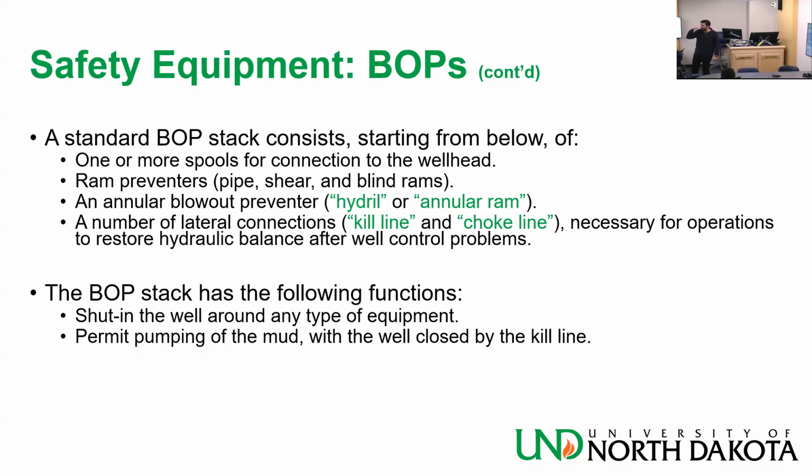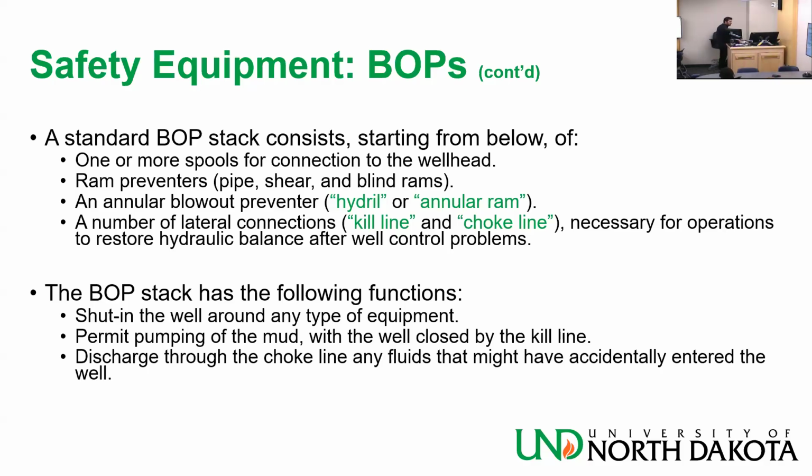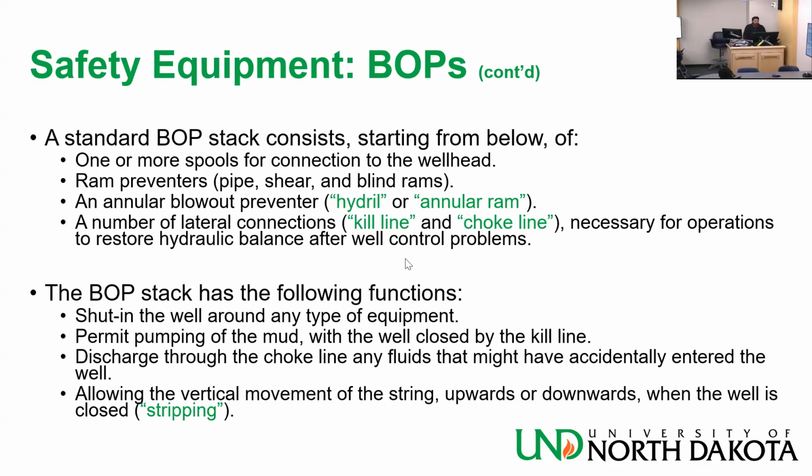Circulating the fluids that got in out is done through the BOP, with the BOP closed. It allows you to do that. Discharge through the choke line any fluids that might have accidentally entered the well, that's kick fluids. Also, it's not common, but you want to allow vertical movement of the string upwards and downwards. This is not going to happen very easily.